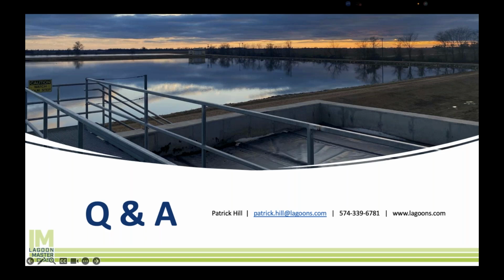I understand covers can cost money because you have a lot of square footage out there, but you only need to cover 3 to 5 days of retention. You don't have to cover the whole lagoon to get effective algae reduction. So that's kind of where I sit on it. For my money, I put the cover out there and forget about it, because it's just going to work, versus having to dye, get on it early enough in the spring, and stay on it all summer long.